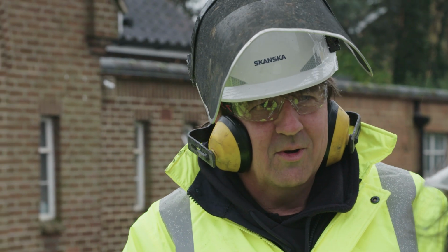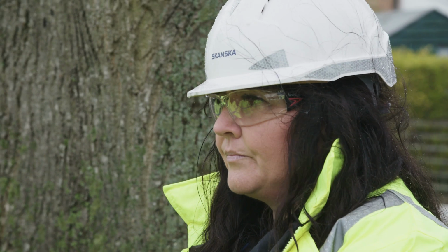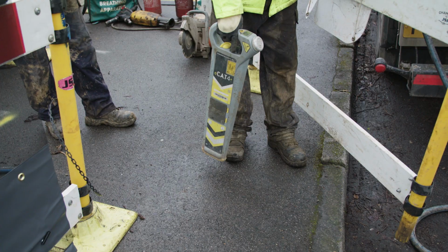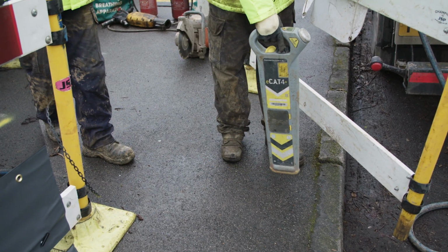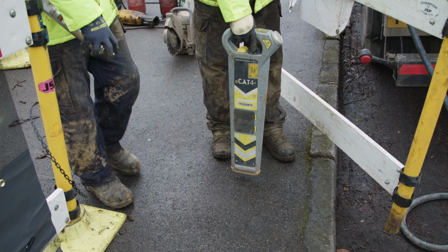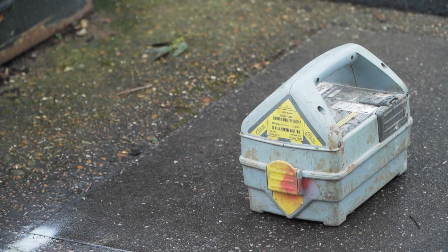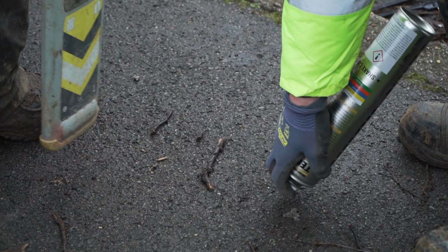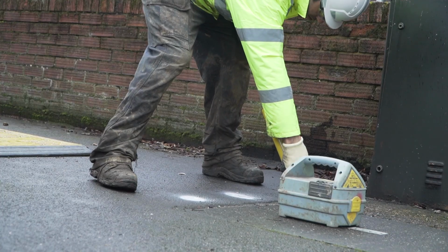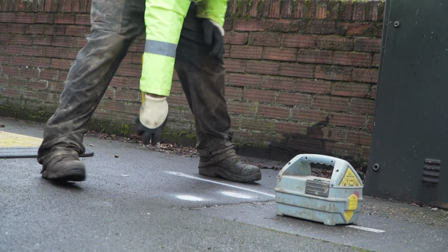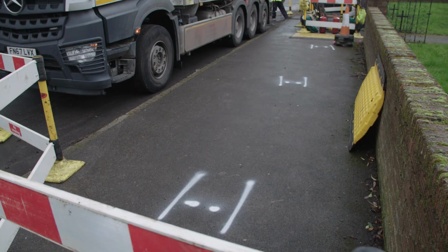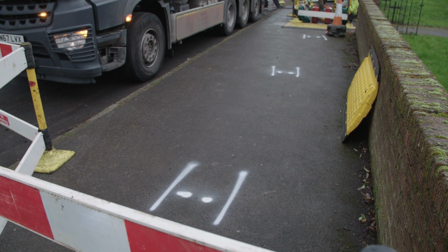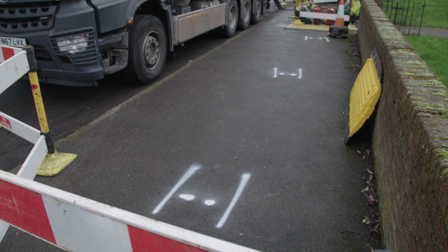The competence of the working team is reviewed, with key personnel having the right qualifications and experience. The USAP also ensures a CAT and generator scan has been completed in all modes, including depth, using all appropriate accessories. All services are checked to confirm they are correctly marked, including encroachment lines. The different levels of survey required are assessed and carried out based on the risk profile of the work